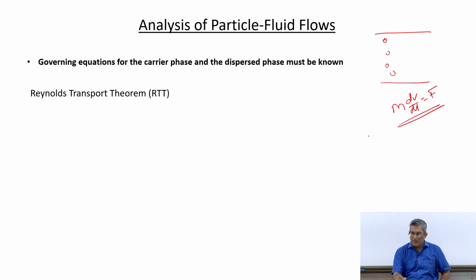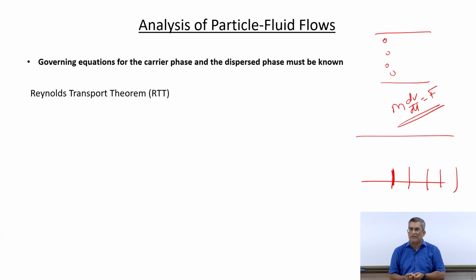Rather, if I have a fluid flow in a channel, I would like to calculate, say, at this location, then at this location, and so on. So, you stand at one location and you want to calculate what is the drag force there. This approach where we considered the ball is based on Lagrangian tracking of the particles, while this approach where you stand and you want to see the fluid flow behavior is called the Eulerian approach.